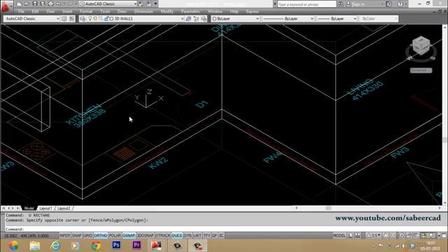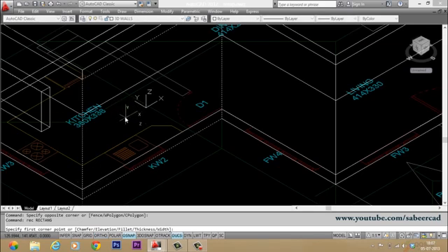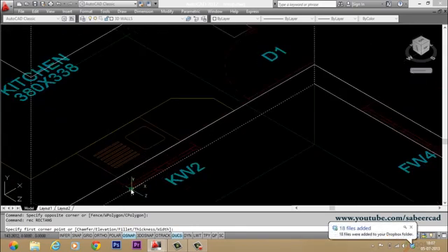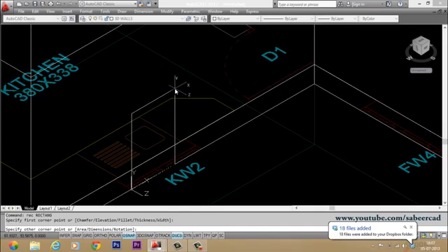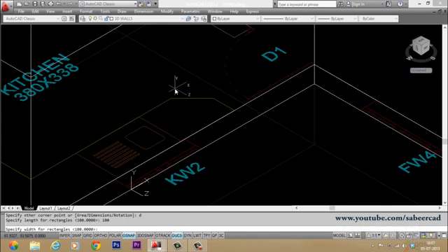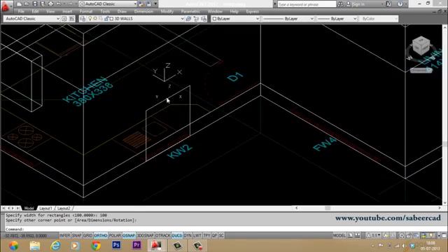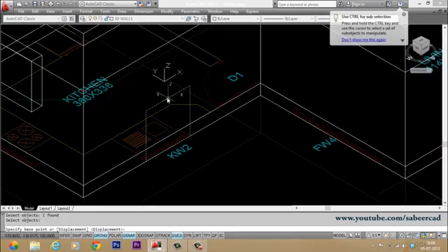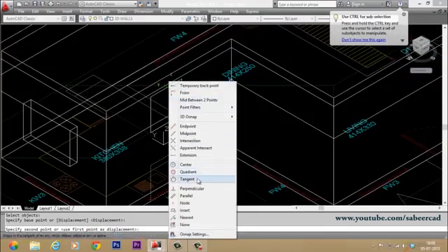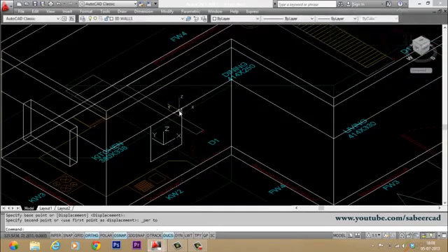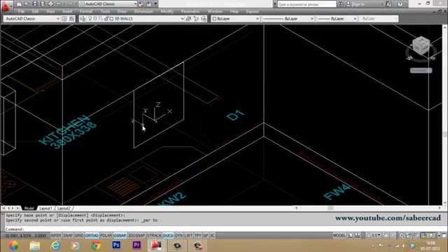Now let's create a cutout on this face. So I'll start with the rectangle command. I'll highlight this face because this is where I want the rectangle to appear. Now take the cursor on this corner and you can give the dimensions. Go to dimensions and you give a width of 100 because it's a 2-panel window, and height of 100. Just fix the opposite corner here by clicking. Now move. This is the base point and you select the second point at the lintel level. Just take a perpendicular.